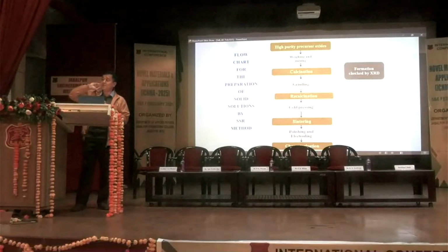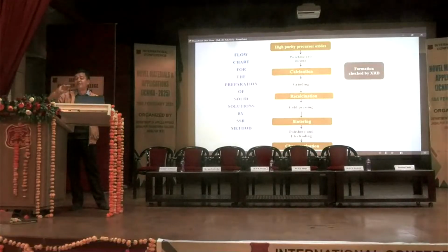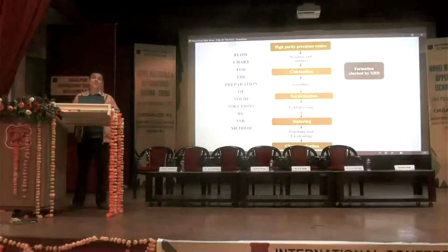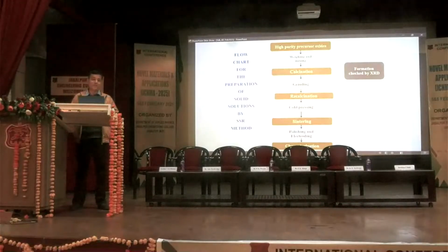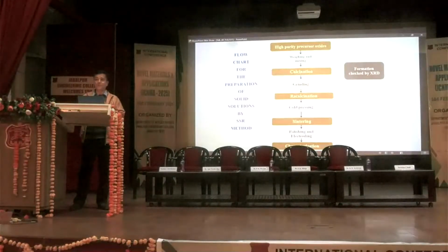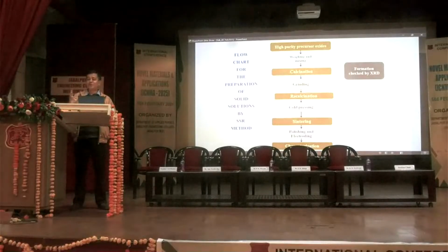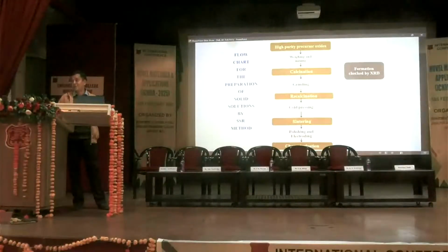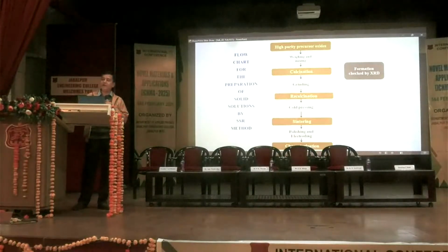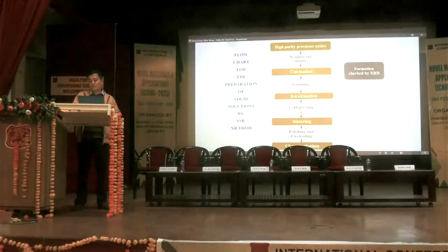Otherwise, due to casualness or not knowing the actual value of the melting point, you increase the furnace temperature to more than 1,000 degrees, and suddenly the chemicals will melt. So don't do that. Before starting the preparation, you should properly know the melting point, when it will mix, how you will check the formation, and how much time is required for the proper thermal analysis or chemical mixing of the sample. And if you are satisfied with the XRD, then you move on to the next process.